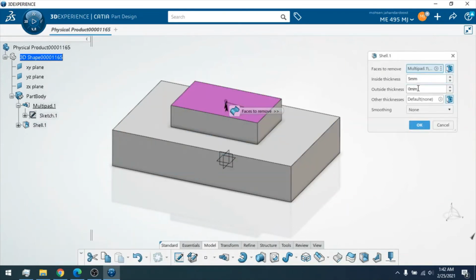Then you can define the thickness to the outward. So if you want, let's say that your profile, you want to sit down at the middle, you can put 5 millimeter in the other side, so you get a 10 millimeter total thickness, and the profile that you created is at the middle. So right now I just keep it at the 0.